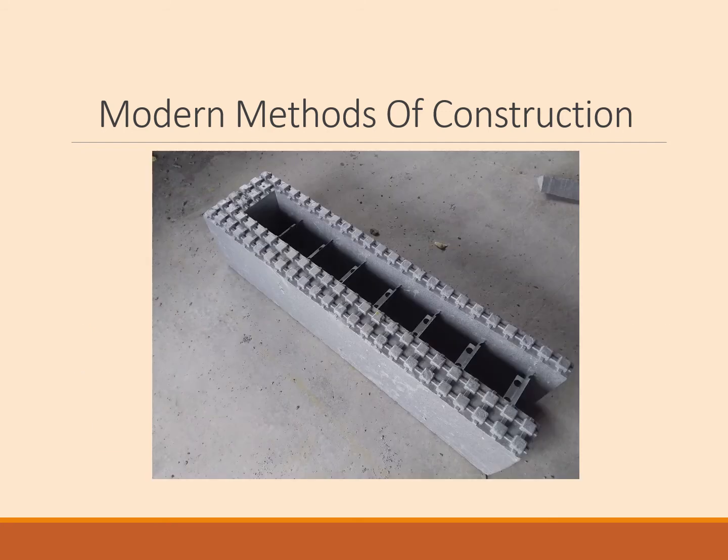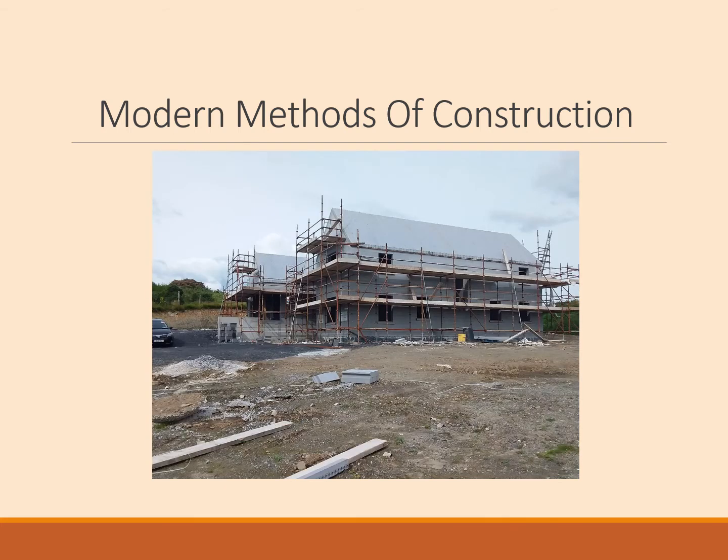Here you can see the preformed top of the EPS. This provides the interlock of the blocks. Concrete is generally poured in stages, and this is allowed to cure before rising another lift.